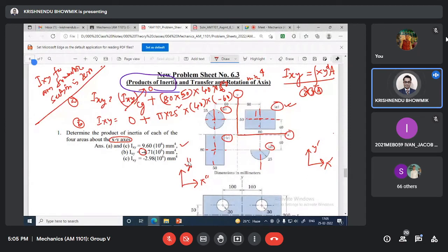That's why in reality, when it is undergoing some deformation, some torsion, some bending, we calculate with respect to the centroid, neutral plane. That is the reason many times we have to transfer the coordinate axis using parallel axis theorem. Sometimes to get the maximum I and minimum I, we have to rotate also. Why? Minimum I is important because if I is a higher value, there is more resistance, and if I is a lower value, less resistance.